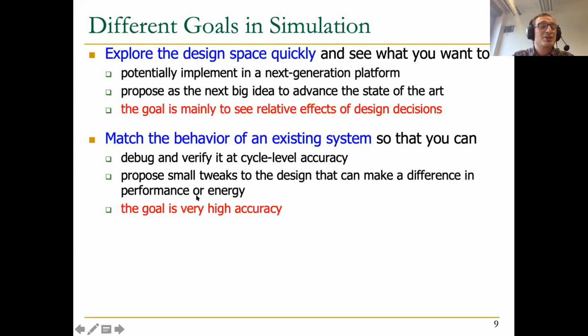Even RTL is simulation. So whenever you design RTL, this is not the real hardware. Keep that in mind. Actual implementation is different from RTL. RTL is a representation of what's going to be implemented. What actually gets implemented may be different from RTL because the tool underneath did some transformation into the layout, let's say, in a different way than what the RTL designer actually envisioned it would be implemented. Right? As a result, you may actually get a different timing in the end. If someone is taking an RTL and translating it to a custom layout in a real system, then again, there might be a difference between what the designer interprets and what the RTL coder decided to put in, right? So there may be differences in interpretation and implementation. So even the RTL doesn't exactly match the behavior of real systems.